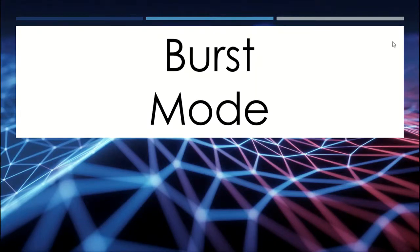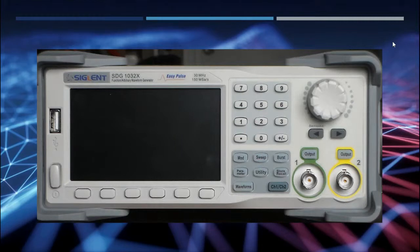The final type of waveform that we're going to look at is what's called burst signals. So we're going to have to set the waveform generator in the burst mode. In order to do that for the Siglent SDG 1032 Arbitrary Waveform Generator, we're going to need to press this button here in order to create our burst type signals. Let's go ahead and take a look at the type of burst signals that the SDG 1032 waveform generator can produce.